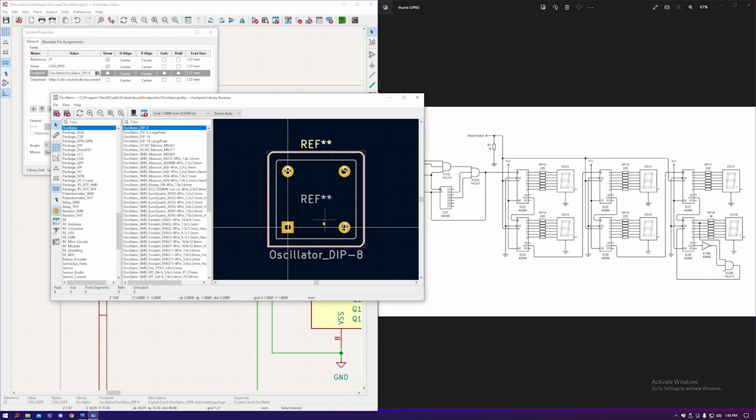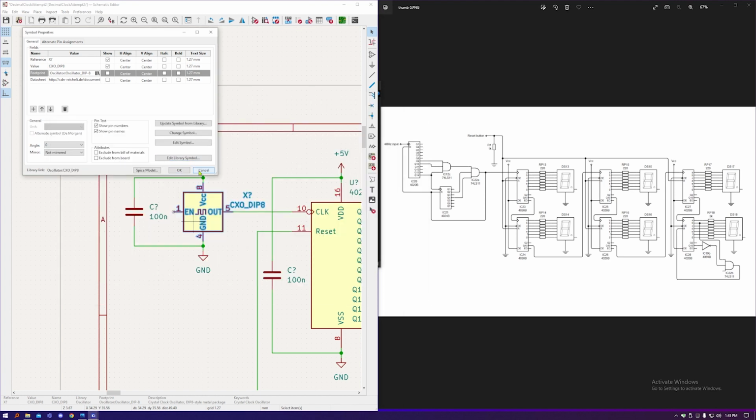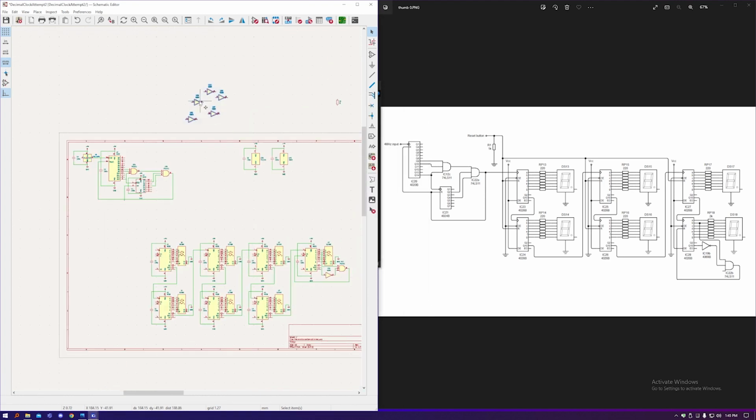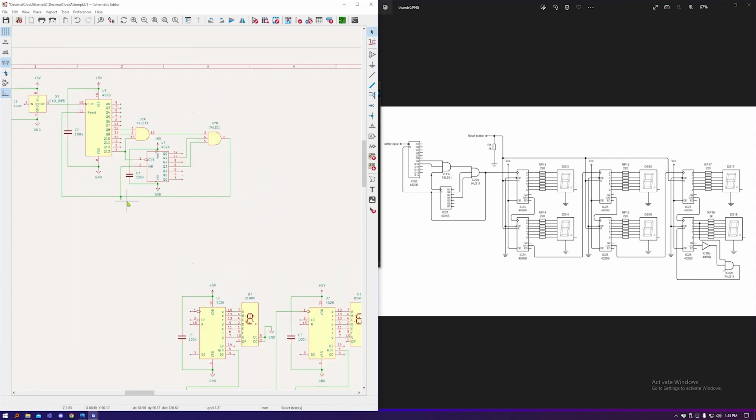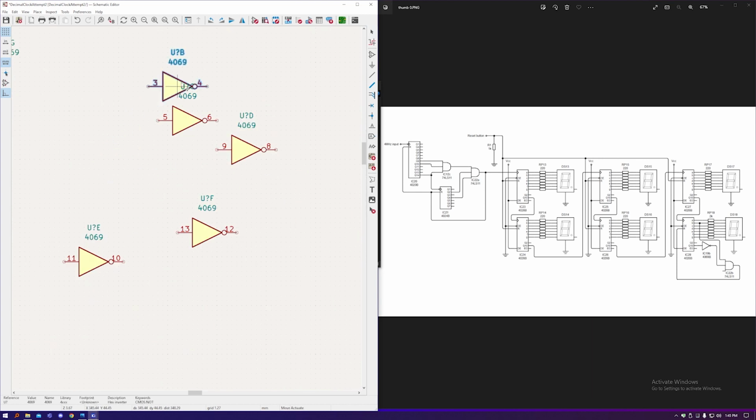It does come with one, but I'm not sure whether I want to solder the oscillator straight into the board or whether to put that in a socket too. I think the oscillator I want to use has very short pins that pop out of a socket, so I will solder it straight in actually. I will leave that as it is. Next, let's get the 5 inverters that we're not using and put them in a nice order.